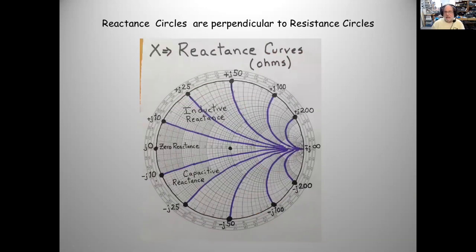Okay, so the reactance. This is a little trickier. So reactance is also in ohms, but it's how capacitors and inductors behave in an AC circuit. So I don't want to go too much backwards into how they behave, but if you have ever studied conductors like coils, as soon as current goes through a coil, it generates a magnetic field. That magnetic field opposes changes, and you get into some interesting things referred to as inductive reactance and inductance. Same thing with capacitors, but they behave differently.